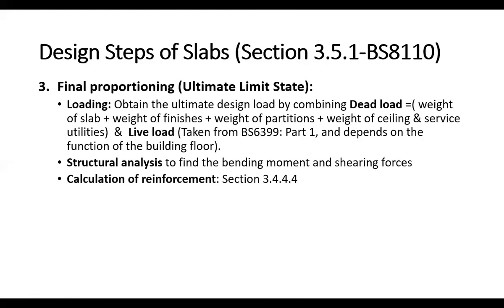After you get the bending moment and the shear force, we have to design for reinforcement. For calculation of reinforcement, we use section 3.4.4.4 in the BS code. You design for reinforcement in the short direction only if you are dealing with a one-way solid slab, or you will design for both directions if you are designing two-way solid slabs.